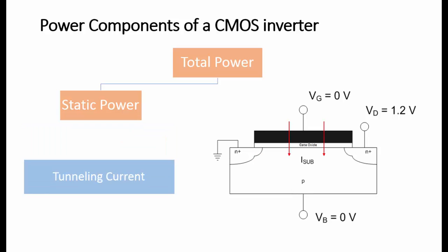The gate oxide, which serves as insulator between the gate and channel, should be made as thin as possible to increase the channel conductivity and performance when the transistor is on, and to reduce subthreshold leakage when the transistor is off.